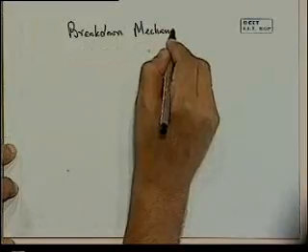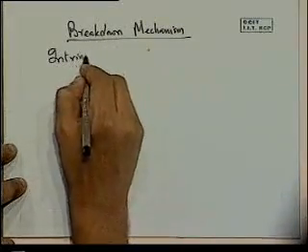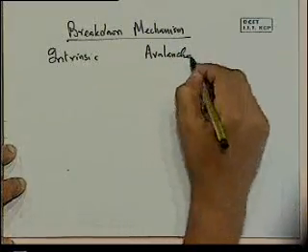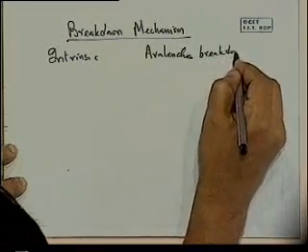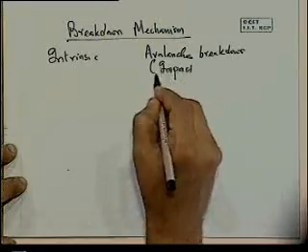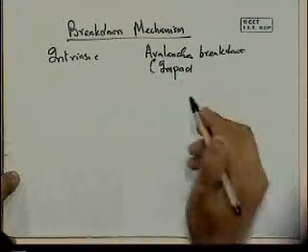When we talk of intrinsic breakdown, what we are referring to is something similar to our idea of avalanche breakdown that we saw in diodes, right? That is basically impact ionization. One ionizes two and then it goes on and it's out of control, the avalanche we saw.